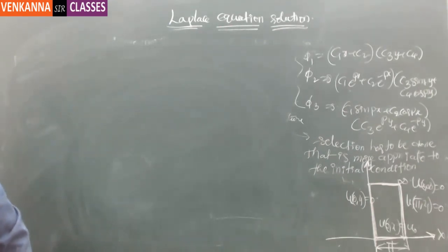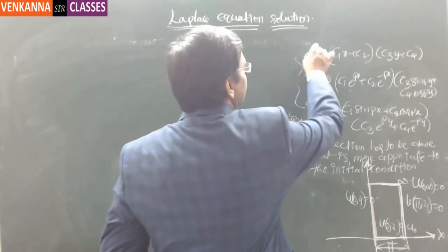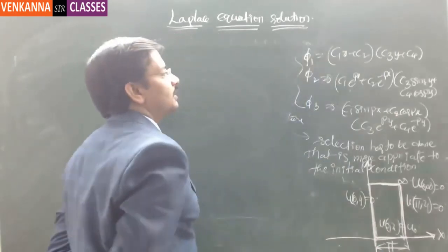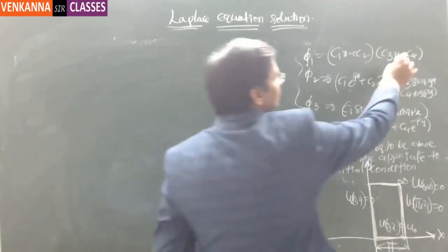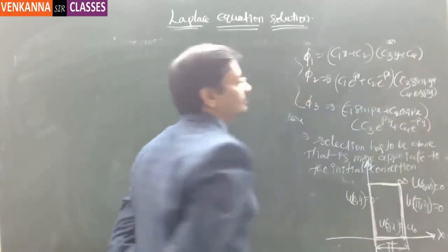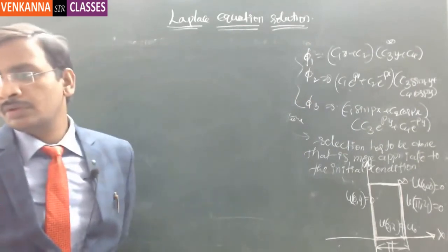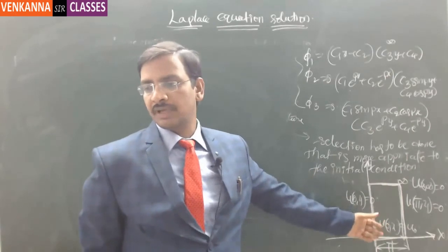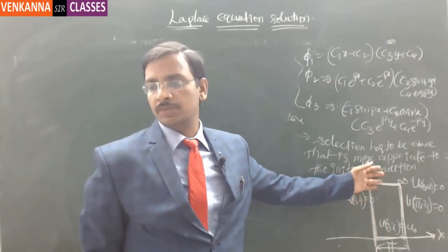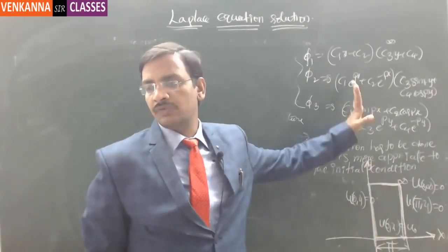Lizu, why did you select that option? So that solution will not fit for us. Why? Because in this equation, if you notice, at the boundary condition where y tends to infinity, this value is going to become infinite. But ideally this temperature is 0, because as you keep moving from the x-axis, the temperature comes out to be 0. So this won't fit for us.